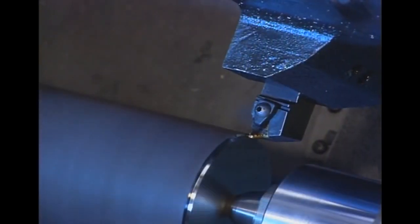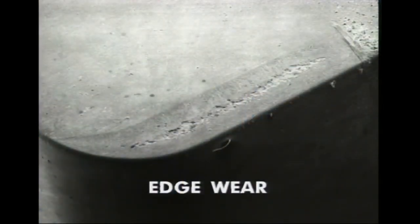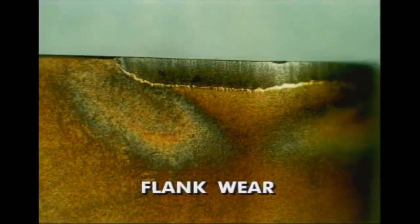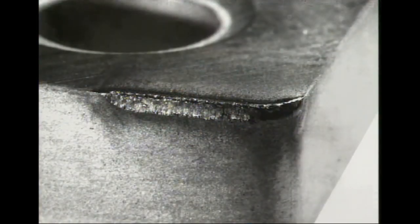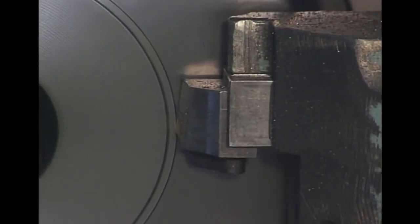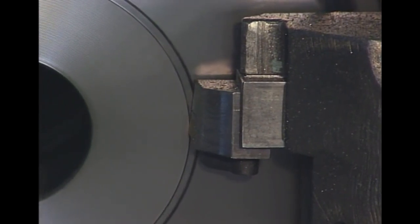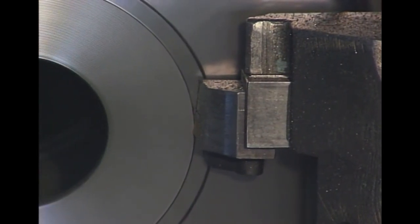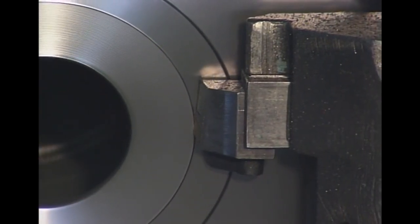Aside from breakage, cutting tools wear in many different ways. Edge wear and flank wear are both a normal and slow type of tool wear. In carbide turning of steel, it often occurs after 15 to 30 minutes of cutting. If the work material is highly abrasive, such as with certain cast irons, this type of wear will accelerate. To correct this problem, select another more abrasion-resistant tool grade.